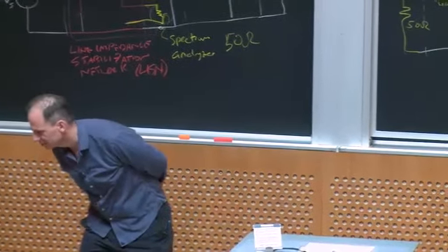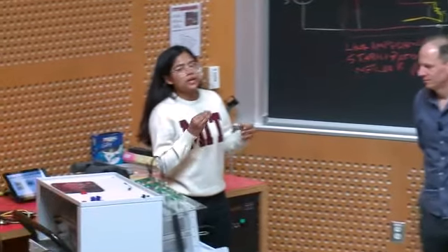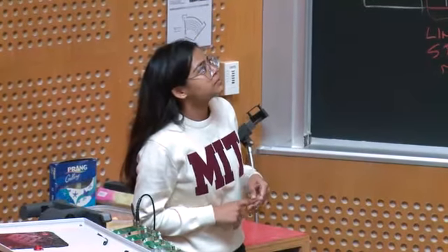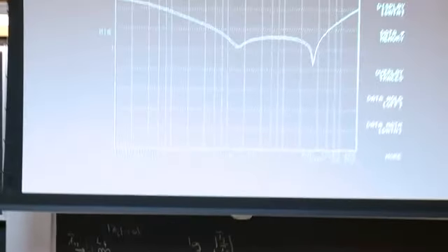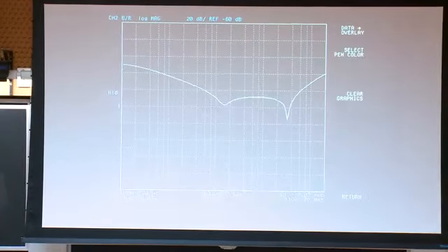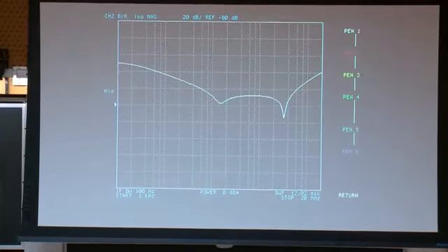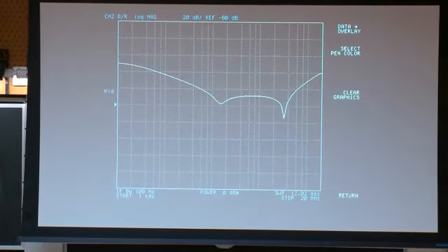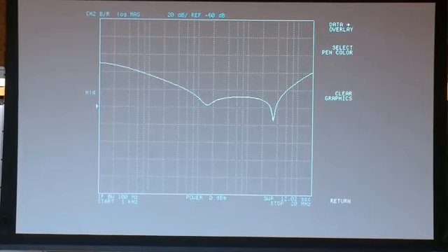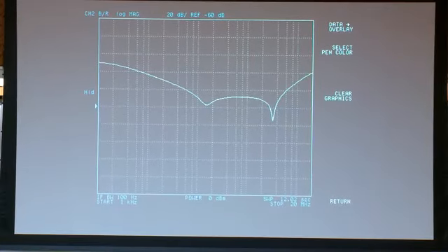So this is a filter where we are not careful about the capacitance and the inductance. Right, so this is bad. This is parasitic capacitance and parasitic inductance. And so this is the attenuation of the filter. We can see that the filter attenuates on a range, and by the way, we're going from 1 kilohertz to 20 megahertz here. You can see even before we get very far out, the filter ceases to attenuate and then it gets bad, right? And these were the good filter components, but we're just getting bad results, okay?